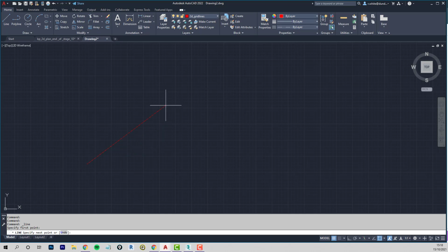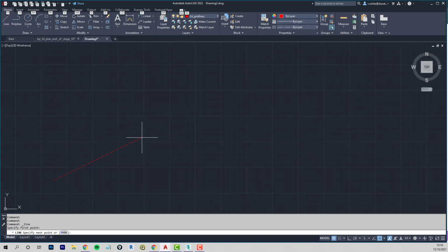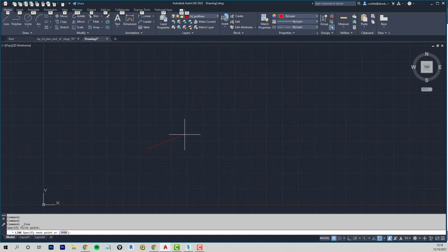I'm just going to start the drawing anywhere at this stage, just for an example. So just left click, and I can see that the line is broken up. If I zoom in, holding shift and rolling the mouse, getting closer to my line, I can see that it's definitely using this center line type. But I want to draw horizontally. I could hold the shift key and it forces ortho temporarily. Let go of shift, it goes back to free. Or I could put ortho on here and it will stay on.